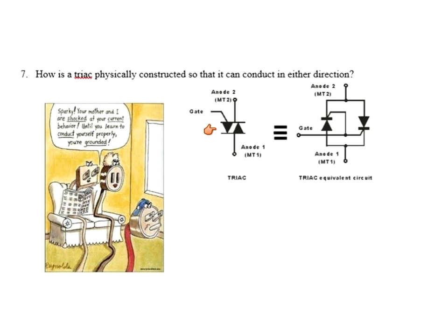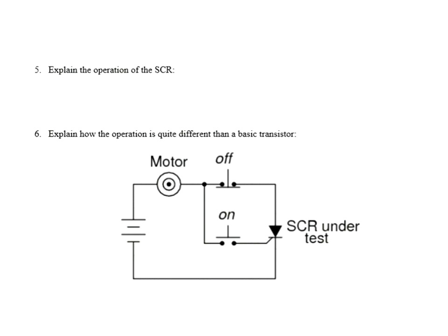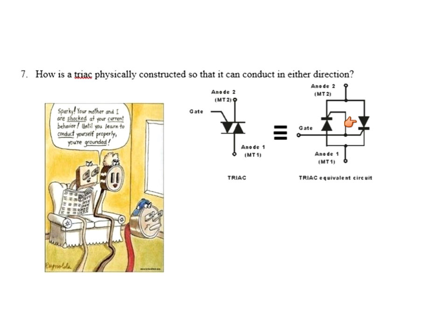Look closely. Let's see, where's the schematic diagram? There's an SCR right there. Then when you look at this over here, you can see one. There it is. But if I flip them over and tie them together in parallel, back to back, and then tie the gates together, I have essentially a triac. That's what it is.